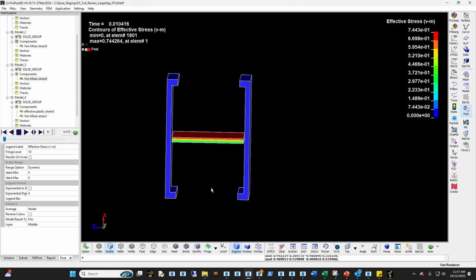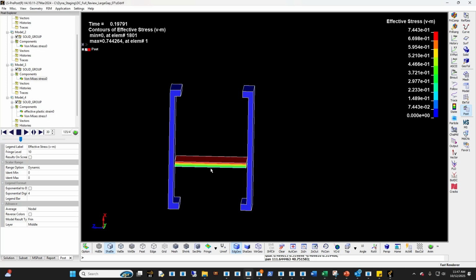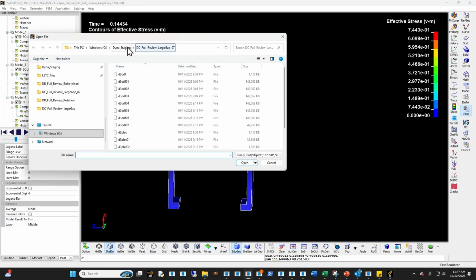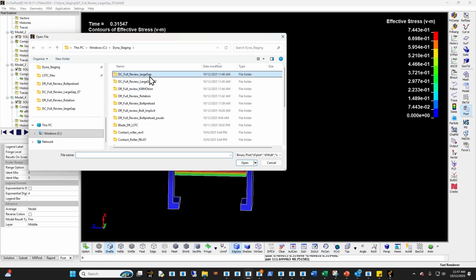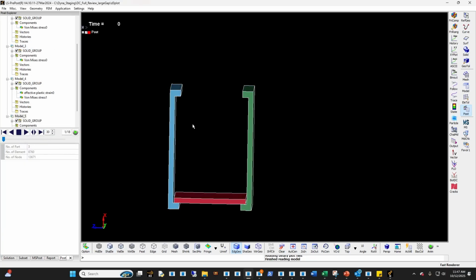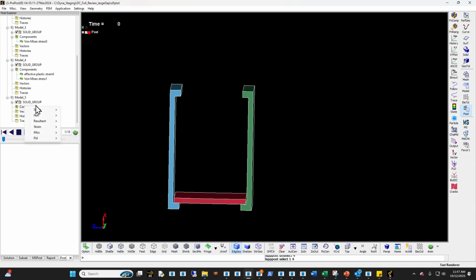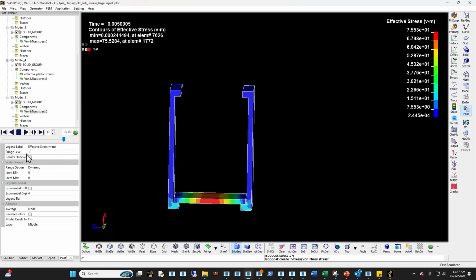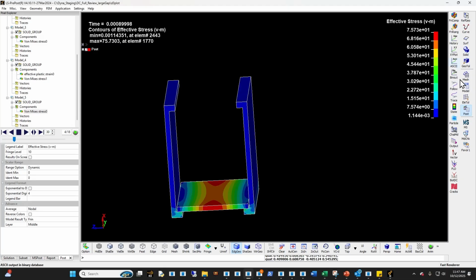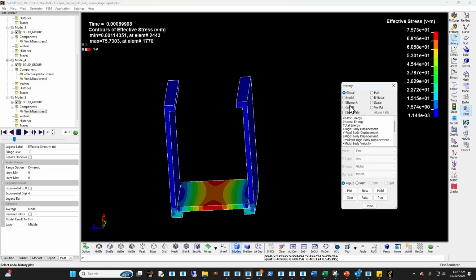And that's something that we're studying. Usually, you can play around with this number depending on your initial conditions. What you don't want is, at the start of the transient analysis, to have some ringing in the system. To demonstrate that, I can show you if I use the large gap. If I look at this one right here, you see how there is still ringing in the system. Because I didn't damp it out during dynamic relaxation, the ringing still exists, right?